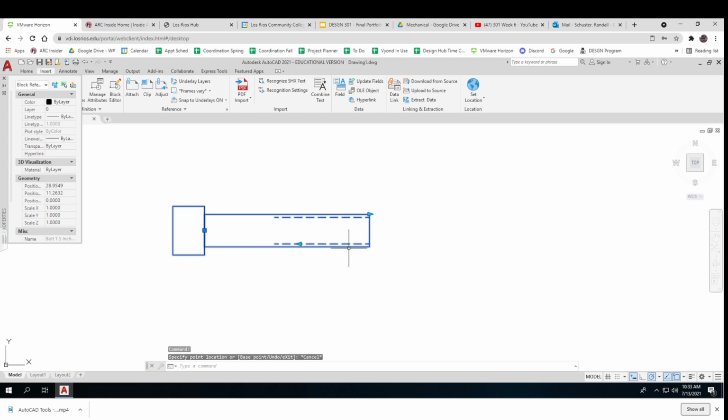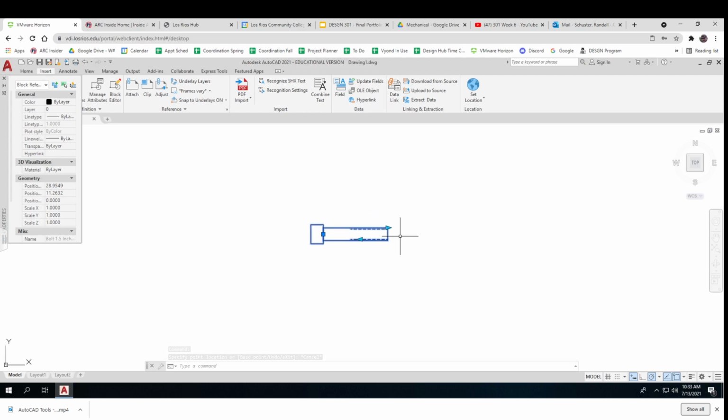UNC. But you can, in your attributes, set it up so that this particular one, you double click on it and you tell it what that attribute is. And then when you export that to your machine tool, it knows to pick this thread form or whatever. And whether it's a die or a single point cut, that would be up to the machinist to program in or to read off of their defaults.